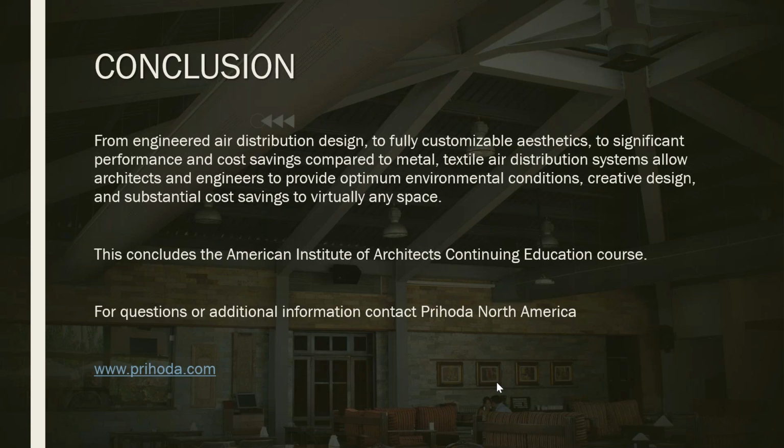Okay, the next question is, what is the static pressure drop for a fabric duct? How do you size your air handling unit from a static pressure standpoint? Sure. The way that fabric duct works is on static regain. So whatever we design at the inlet, that is what you can expect through the fabric. Now, if you do have some offsets or fittings, like a trunk line and then two branches coming off of that, there will be some static pressure loss where it's transitioning from the trunk line over to the branch run, but it will balance itself out in the end.